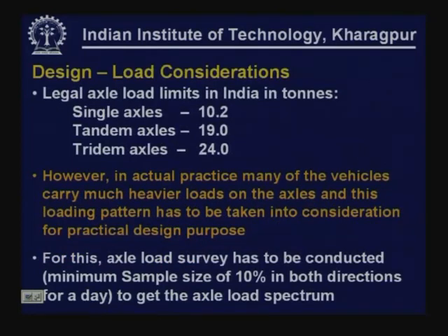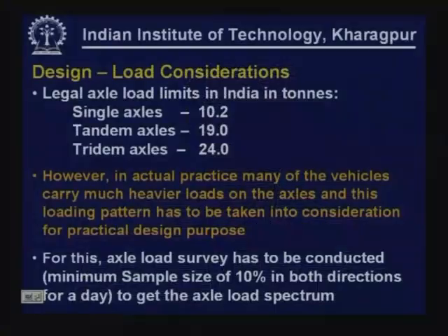We know that the legal axle load limits in India for single axle load is 10.2 tons, tandem axle is 19 tons, tridem axle is 24 tons. However, in actual practice, many of the vehicles carry much heavier loads on the axles, and this loading pattern has to be taken into account. We cannot rely on these legal axle limits, because we know that much heavier loads are going to be applied. We have to take that actual practical loading pattern into consideration and design accordingly.